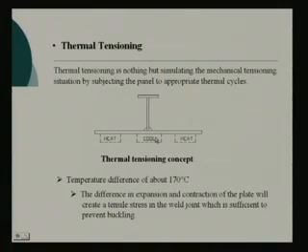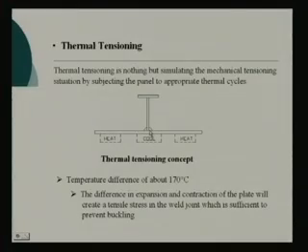Now, you have an additional problem: you have to provide some heating and, simultaneously, cooling. In side heating it was only additional heating, in heat sinking it was only cooling. Now, here you have both, right. Not only that, you are cooling it just below the weld where welding is being done. So, you run the risk of damaging, quenching this part of the plate if it is a thinner plate, and thinner plates are more prone to buckling.